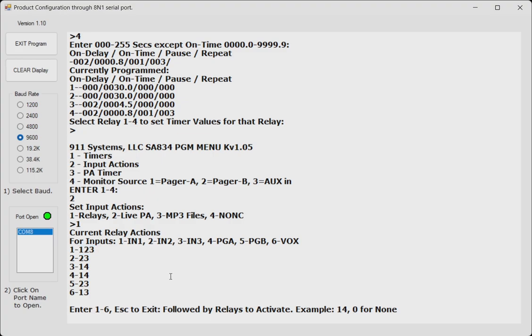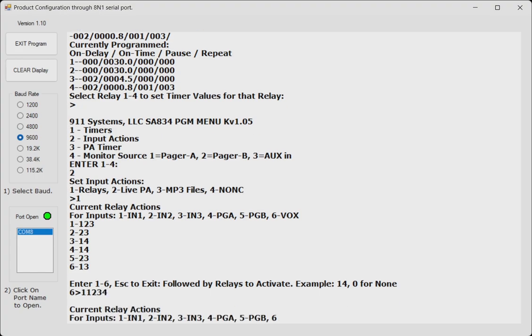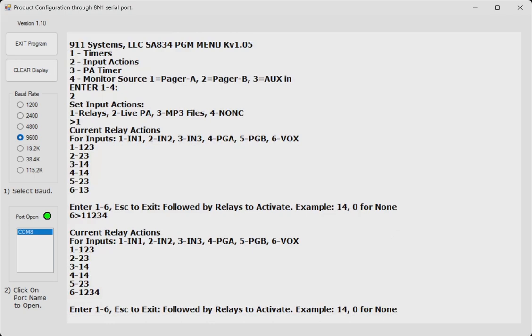So these relays, if you need to change a relay, you can just press the relay that you need to change. I'm sorry, the input that you need to change the relay settings for. So let's change the relay settings for audio detect. Let's say you want to turn on all 3. So I hit 1 twice, that's my fault, but the system knows that you can only turn on relay 1 once. So you can see now if there's an activation by Vox, all 4 relays will activate and go down their time on their scheduled time settings. So let's go ahead and escape out of relays because we've pretty much got that one explained.